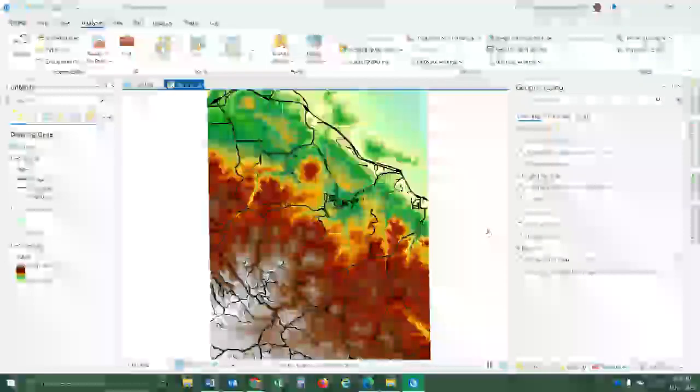You almost never change that. And then you want to make sure that you're not messing with any geoprocessing settings, because that can mess up your work by doing some funky resampling, and you just don't want that. So I'm going to hit OK, and that is step 1.